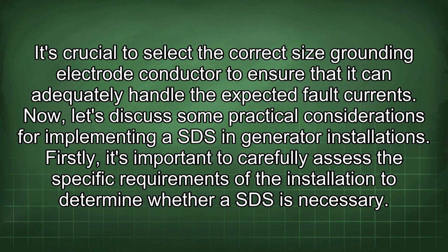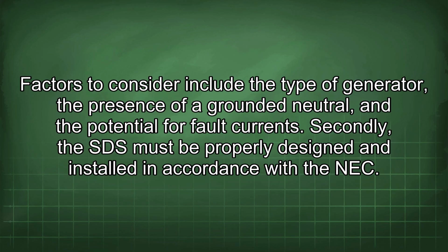Now let's discuss some practical considerations for implementing SDS in generator installations. Firstly, it's important to carefully assess the specific requirements of the installation to determine whether SDS is necessary. Factors to consider include the type of generator, the presence of a grounded neutral, and the potential for fault currents. Secondly, the SDS must be properly designed and installed in accordance with the NEC.